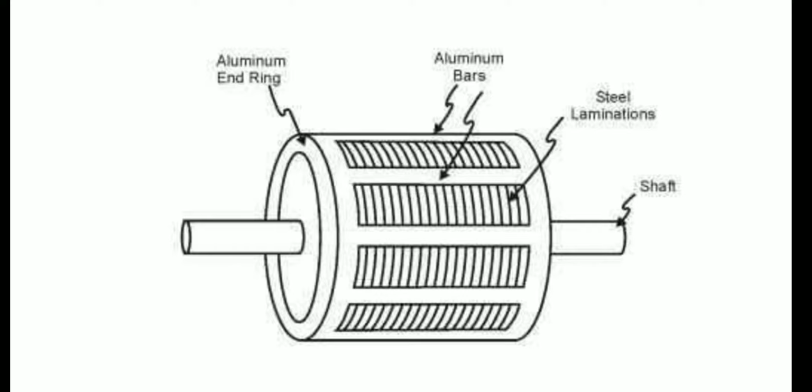In the rotor bars also, flux is produced due to the EMF induced in the rotor. Getting my point? The EMF induced in these rotor bars will be sinusoidal over one pole pitch. So what is pole pitch? The pole pitch is nothing but the angular distance between the sides of a coil, that is, the sides of the bars. Or else it is also the angular distance between the centers of two adjacent poles.